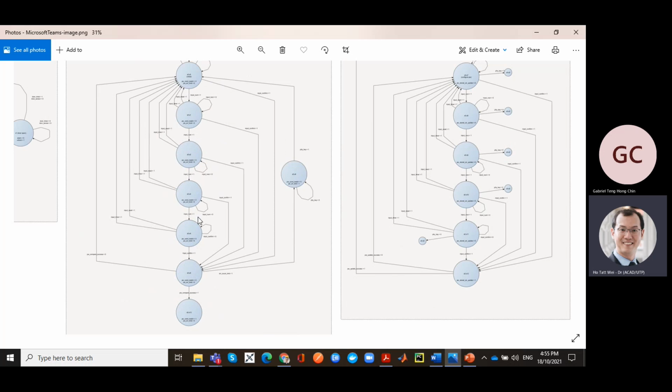If you wanted 3 attempts of 5 keys, the way to do it is you have another state machine that's just doing a counter. Whenever there is a failure, the failure will increment the counter to 1. Another failure, the counter goes to 2. Then the third failure, the counter goes to 3. When the counter hits 3, there's another signal here. Instead of allowing yourself to go through here, you just jump straight into this state. You see or not?